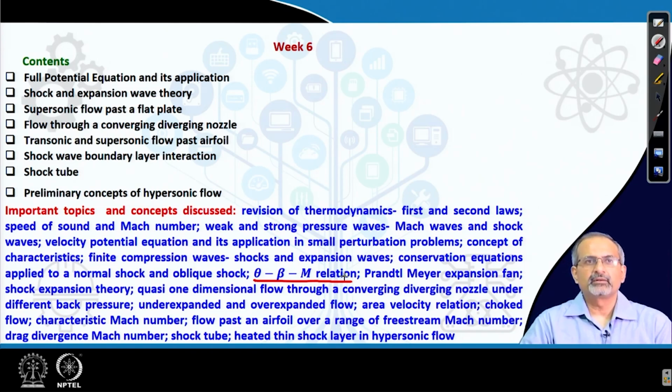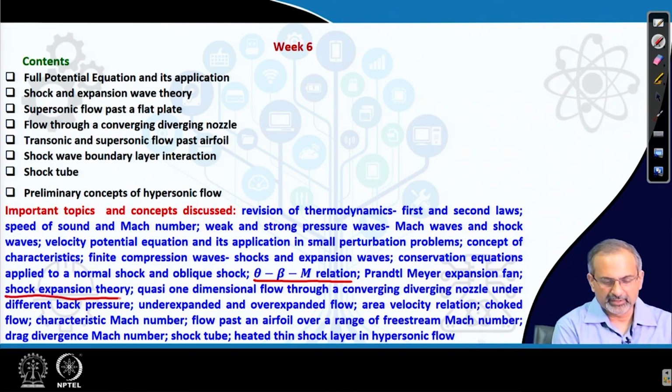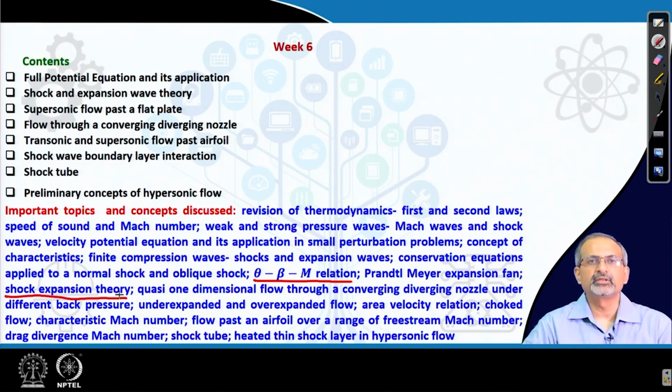Prandtl-Meyer expansion fan theory was discussed, and once we were comfortable with shocks and expansions, we applied them to shock expansion theory, which we found to be very, very efficient in predicting the pressure distribution on different geometries applicable to compressible flows like the diamond airfoil, for example.